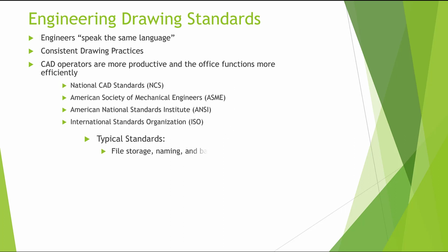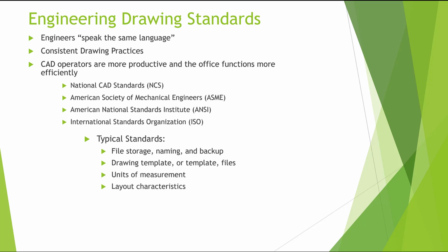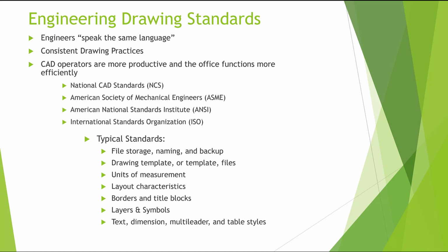Most companies have adopted standards to be more productive. You see a list here, such as naming conventions, drawing templates, units, the layout of views, borders, title blocks, layers, symbols, text, and the way that the drawing is printed.